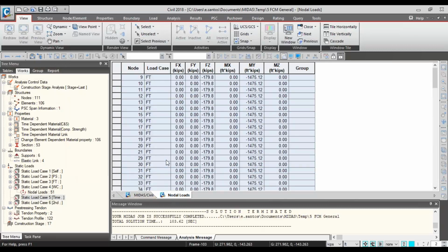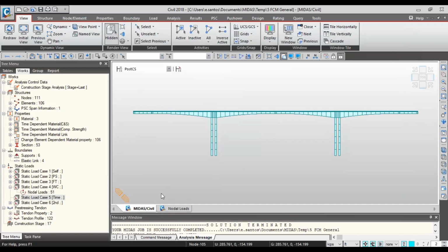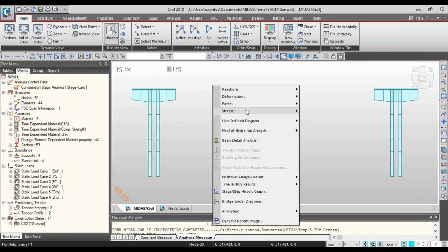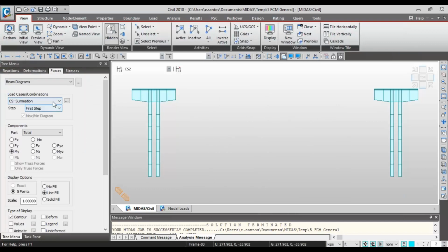Just in case the form traveler changed, the weight changed, those things happen and you want to reevaluate the bridge, you can change that and then the program will automatically change it in the model. So if you want to check a particular stage, you can just select it, and after running the analysis, let's check the different types of forces that are generated.